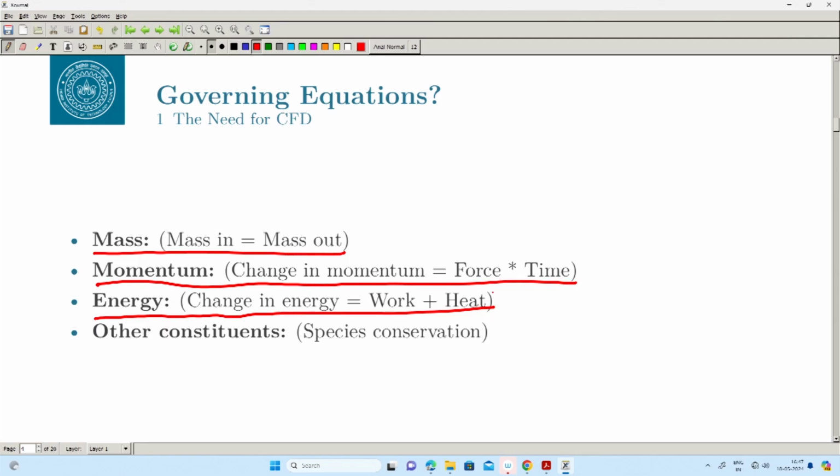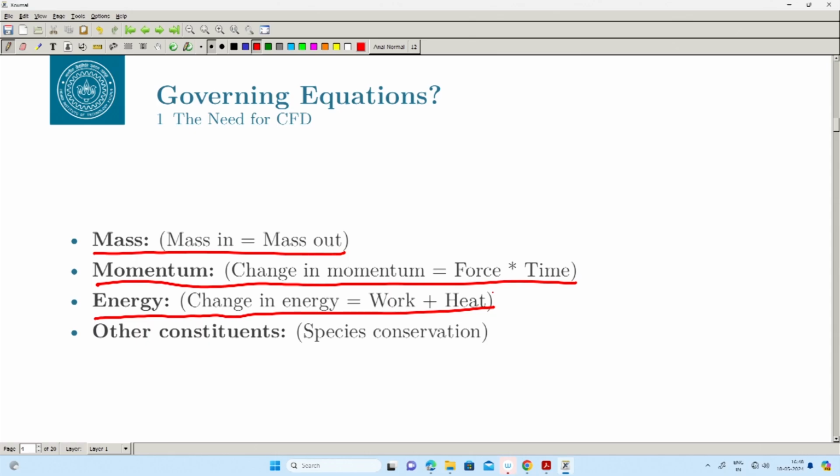We will discuss that aspect in a future class, when we discuss the difference between compressible and incompressible flow. But for now we will say the flow in which the density change is important, we will consider as compressible flow. And for those flows the energy conservation is very important. It is important in incompressible flow also, but it becomes a trivial equation there, because you do not have any thermal energy being added that affects the dynamics of the system. So, you can just solve the kinetic energy conservation, which can be derived from the momentum equation directly. So, we do not solve the energy conservation in incompressible flow normally.